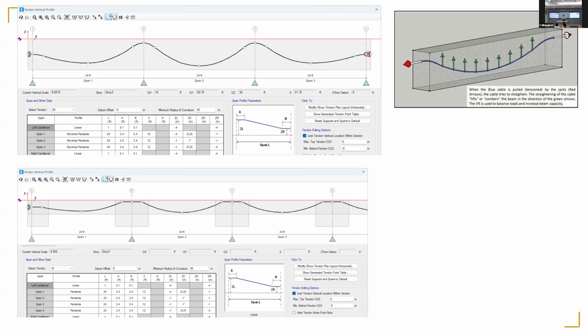And that is a very, very hard thing to do because slabs are complicated and the profiles cannot be perfectly managed. So even if you try very hard, in the end, some tension is likely to develop. So we try to keep it in a certain manner. So stresses need to be checked. You also need to add some reinforcement for accidental tension being developed, and also to take care of the tension developed by loads that you could not balance, like moving load or live load. So this is the basic concept that they will be teaching you, and then you will use that.